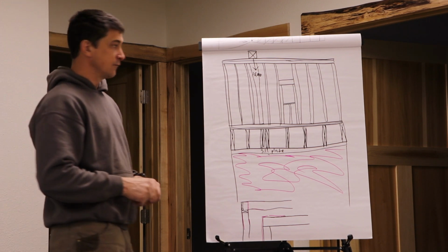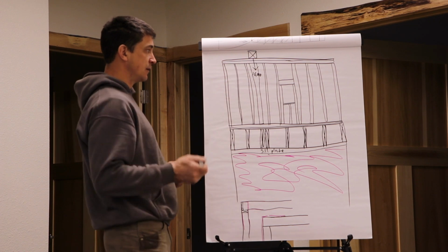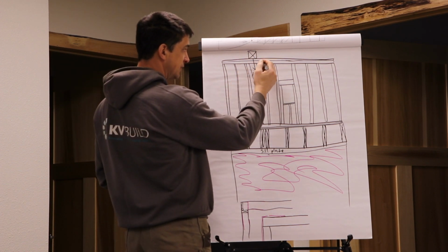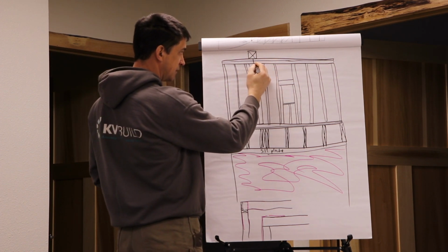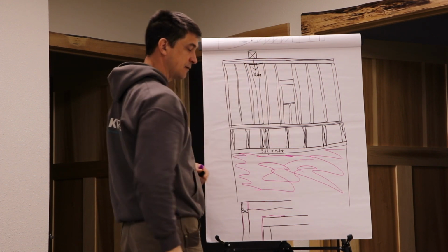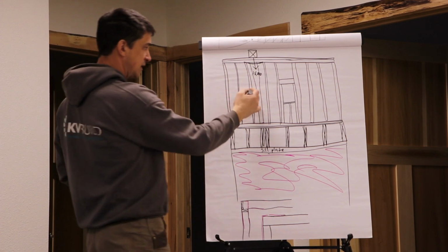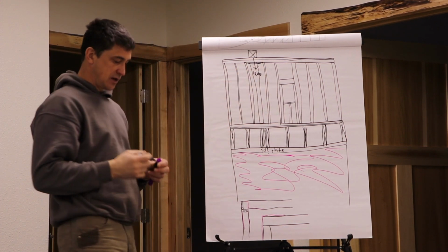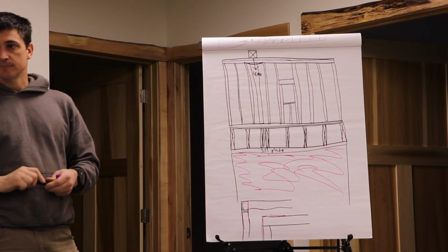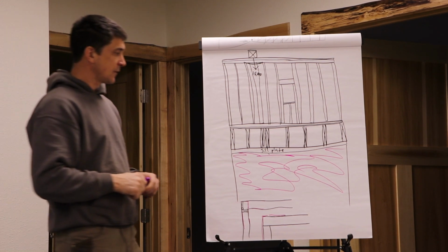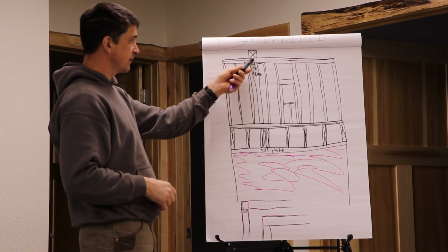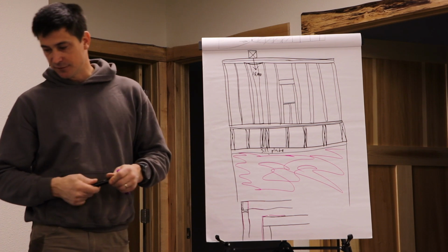If we don't do that, two years after we build this house, we're going to come in here and this thing's going to be sagged in between those studs. These studs will probably deflect, you'll have cracks in your drywall, it'll be a complete mess. So it's very, very important that we transfer loads to the foundation.